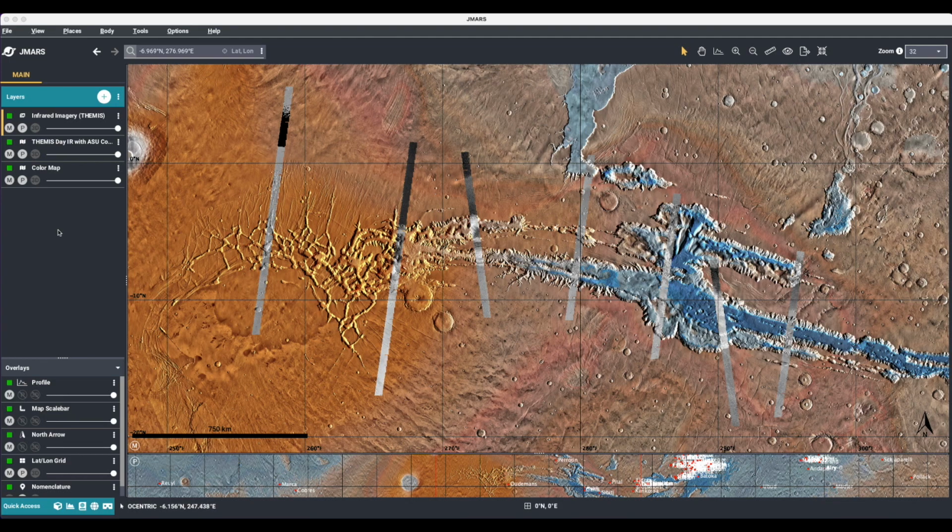You'll notice on your left-hand side you have your layer manager, and each layer that you have loaded has three buttons, an M, a P, and a 3D button. The M stands for main view, that's this top portion. The P stands for panner view, which is this bottom viewer. And the 3D button is for the 3D viewer. So you'll notice also that each layer has the 3D button turned off. If you want to see that particular layer or stamp or map in the 3D viewer, you need to click that button to turn it on.